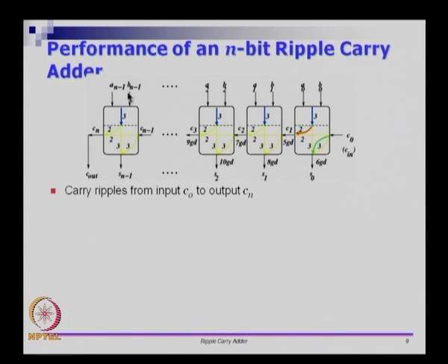You will see that at time unit 3 it will have passed through the first adder, and in time unit 6, Sn minus 1 all the way to S0 would get some intermediate values. So everything from Sn minus 1 to S0 would get some values at time unit 6. However, at time unit 5 we get C1 which is coming through. This C1 can potentially change both sum and carry. So this came in through a delay of 2, so 3 plus 2 is 5, and if you look at this path, this is already coming at 5